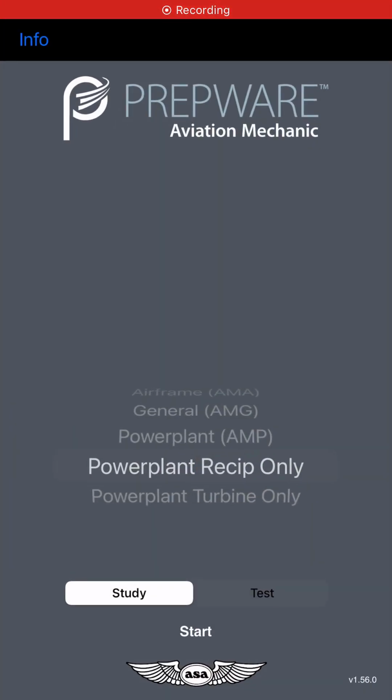Powerplant at cruise RPM. Some oil will flow through the relief valve of the gear type engine oil pump. This is normal as the relief valve is set at a pressure which is lower than the pressure pump capabilities, not the inlet pressure.